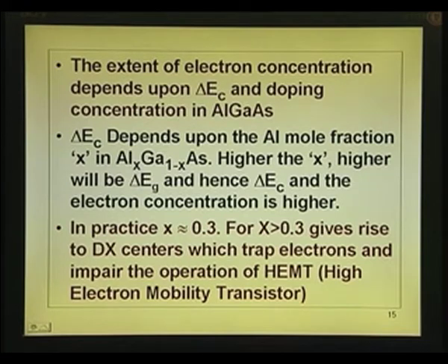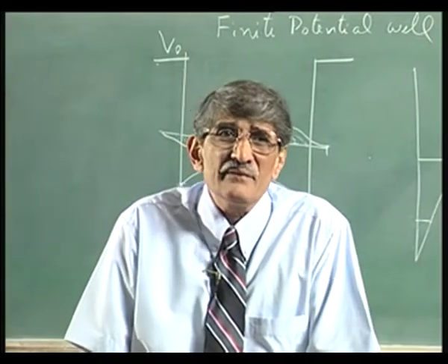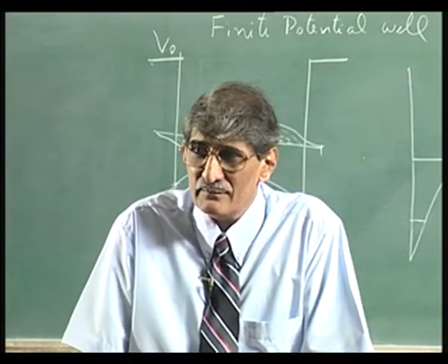Okay. Now, there is one more technological problem. Apart from this, higher aluminum concentration introduces trap centers called DX centers. It also makes it difficult to make ohmic contact.